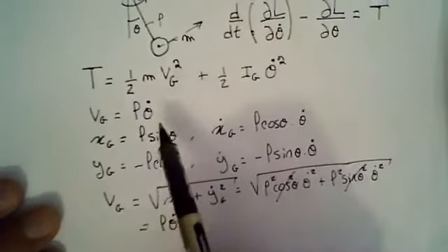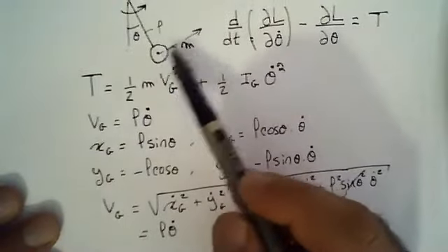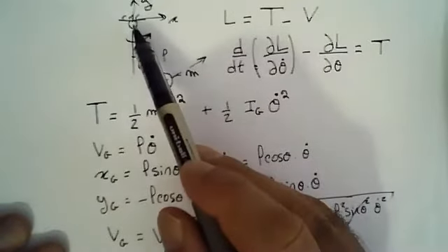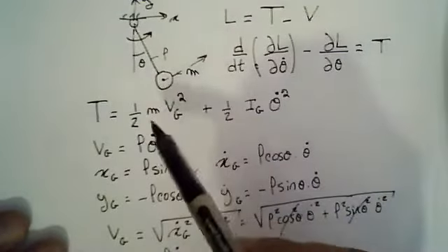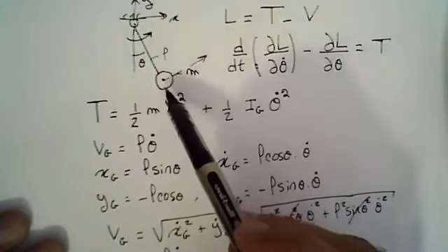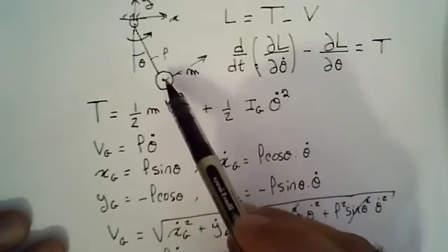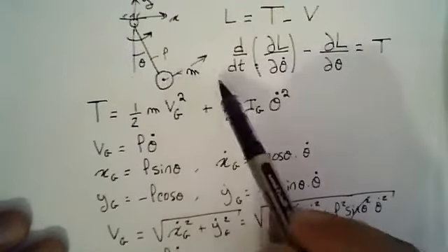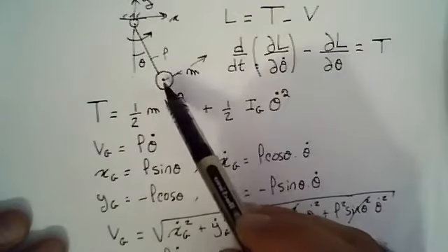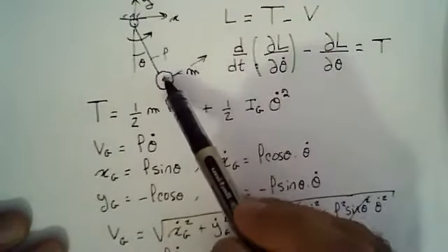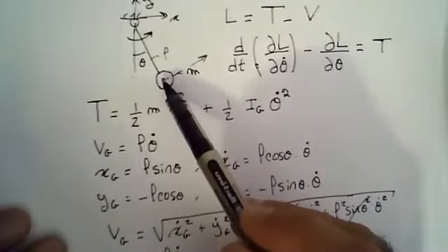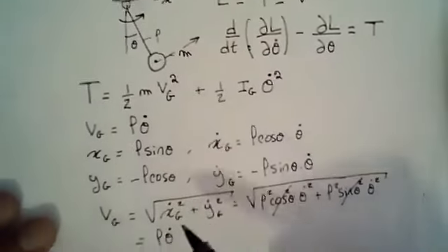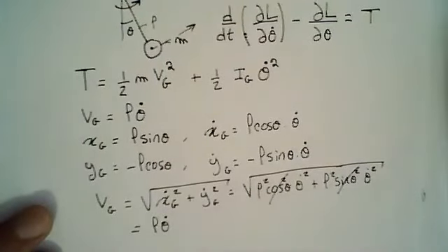So, if you don't see it directly that this is translational, you can just do the basic stuff that we've done, right? So simply express xG, yG. And this is the beauty of Lagrange, as you will see later: once we express the kinetic energy, it's very easy using MATLAB because we can actually put a frame. So if you have a multi-link robot, you will simply put the frame at the center of gravity, find your homogeneous transformation from the start to finish, and the homogeneous transformation will already incorporate that position of the mass, or the center of gravity. So we can differentiate that to quickly obtain the total kinetic energy of the system.